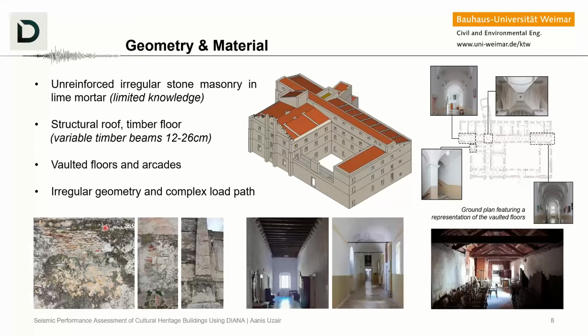Rather, we will work with a large set of material data that will give us a large set of results, which can be used, or the worst case scenario can be used, to identify problematic areas in the structural system. The connections in these cases are unknown, which is why we will not model the connections particularly.